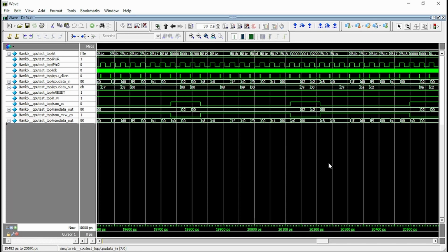So our demonstration model in Verilog seems to be working just fine. No real point looking further into this. If you want to run this, just download the files off the GitHub, stick them into Modelsim, and you'll get the same as this. You can play around by putting in your own assembler code and doing reads and writes how you want, and just check that it's doing what you'd expect. But pretty much here we've got a functioning system with our Arlet 6502 CPU that's got RAM and ROM. It's reading from those, it's writing to those, so we've got a good functioning system.